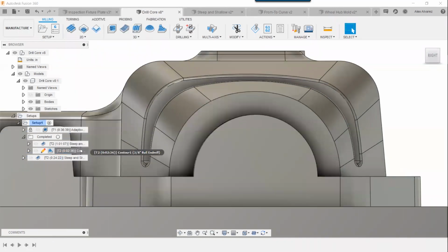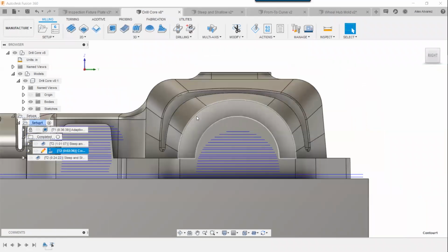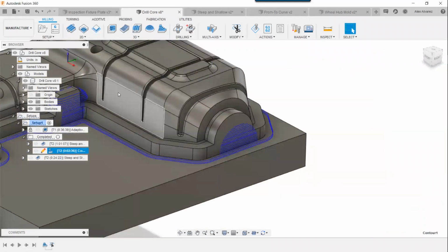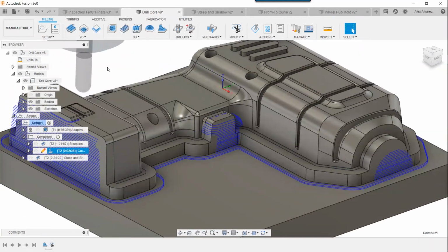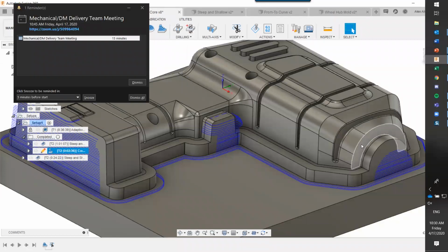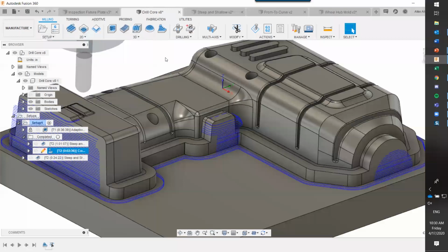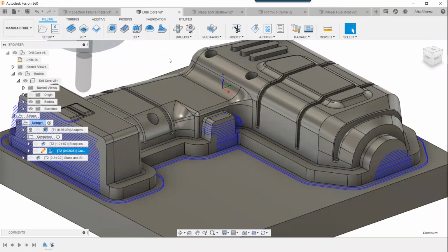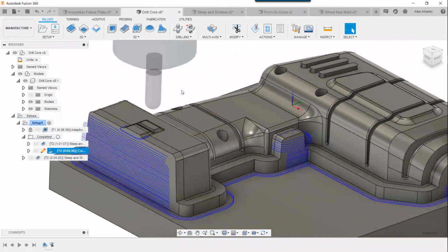An interesting fact here is that a lot of questions we get is, well, what if you make a change to the toolpath, maybe you change up the feeds and speeds, or maybe you change a specific parameter. Is that section going to come back on? And the answer to that is no. I actually changed the feed parameters, and that specific section that was there, it was automatically gone, right? So you don't need to worry about changing parameters and having that section come back on.